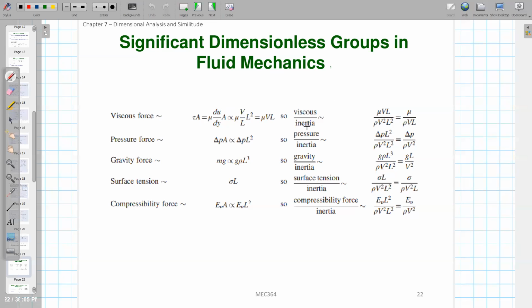And for the inertial force, you can do similarly. What is the inertial force? It is mass times acceleration, Newton's second law. So this rho term is the mass, and acceleration is meters squared per second squared, so you can use that to get the unit. Using this viscous force divided by this inertial force, you get a value, and this value is actually the Reynolds number, because we define the Reynolds number as rho V L over mu. So this is the way we define a dimensionless parameter.